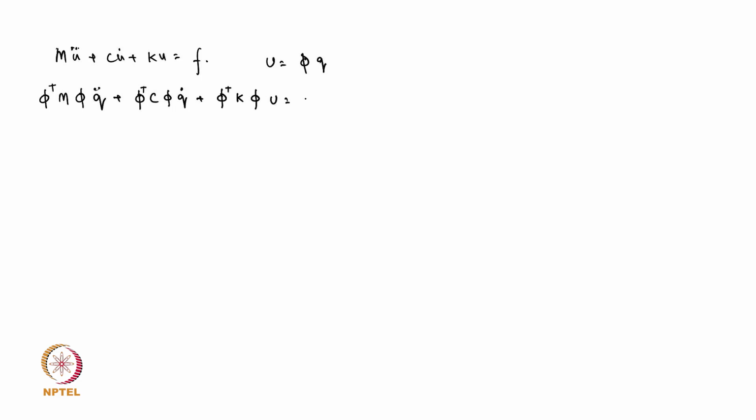M u double dot plus C u dot plus K u equals force. Now I have changed from u equal to phi q. Now phi transpose M phi q double dot plus phi transpose C phi q dot plus phi transpose K phi q should be equal to phi transpose F.